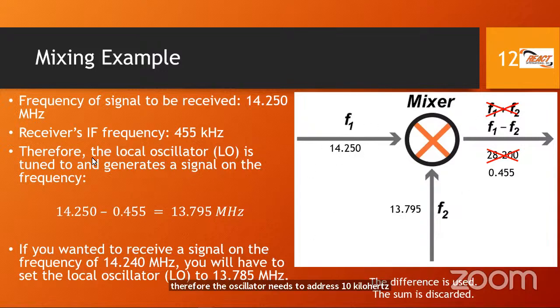So folks, hopefully this example has made it real in terms of the actual circuitry, and that we're not just theorizing in a conceptual view, but we're actually putting some numbers so you can see how the circuitry actually works: bringing the signal into the radio, using a local oscillator to mix or heterodyne, and we end up with a standard frequency for the intermediate frequency IF stage.